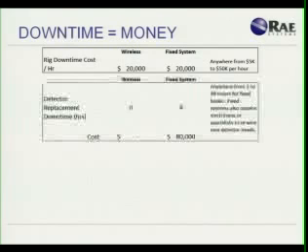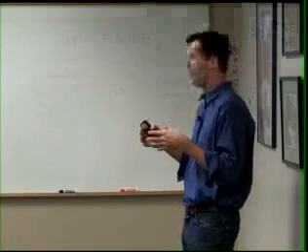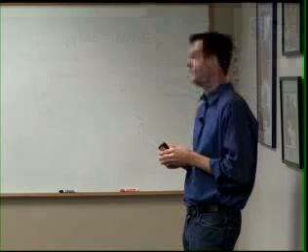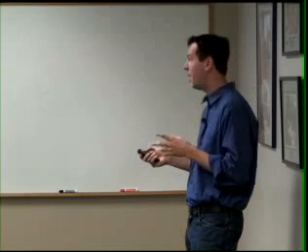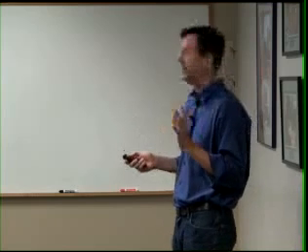So let's say one of your detectors goes down for whatever reason. It's hit by a truck, there's some circuit board that failed for whatever reason. So with a fixed system, you need to have an electrician come out there and fix that, right? You gotta shut down the system, unplug, undo a bunch of conduit, undo the cabling, replace that head, put it back together, restart the system, make sure everything's configured correctly, bump and calibrate. So we estimate it's roughly 4 hours to do that if a head goes down.